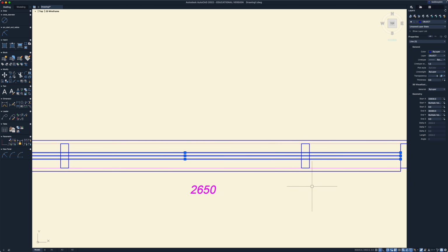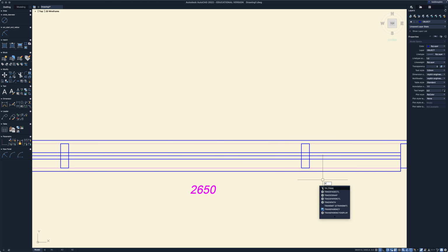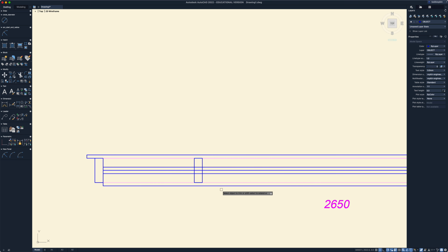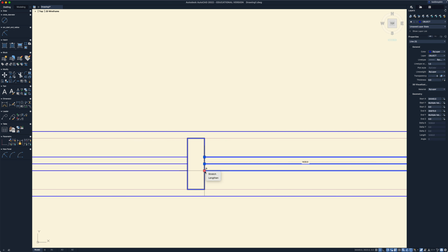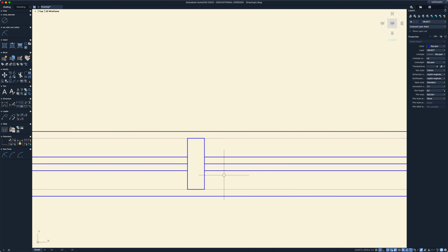And then I would end up just trimming what's in between here. And then this one now I would be able to move over 25. Okay, I'm assuming we'd probably be able to use that stretch command. So STR, I mean.